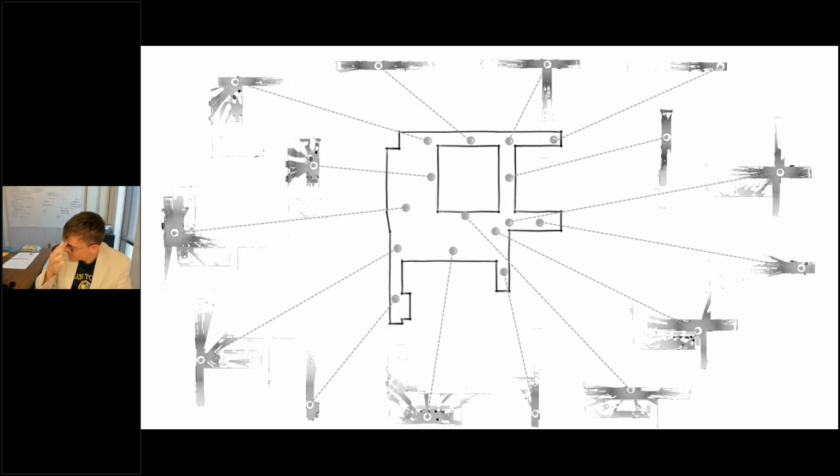Why is that? It's because right now each scan thinks it's the center of the universe. That is the local coordinate system where the center of the scanner is the origin, and this clearly needs to be fixed. So how do we take all of the scanned data that we've collected and merge it together into a coherent whole? This process is called registration.